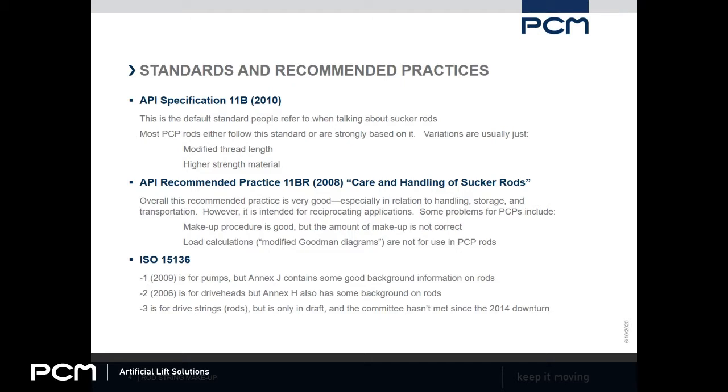Next is API Recommended Practice 11BR from 2008, the latest edition, care and handling of sucker rods. There's a lot of really good material in this document, especially when it talks about handling, storage, and transportation. But I want to make it clear this document was intended for sucker rods being used for reciprocating applications, beam pumps. Some of the issues for PCPs are the makeup procedure. The overall procedure is good, but the amount of makeup is not correct, and there's a couple of details that we need to look at there in the procedure that we'll get into later.